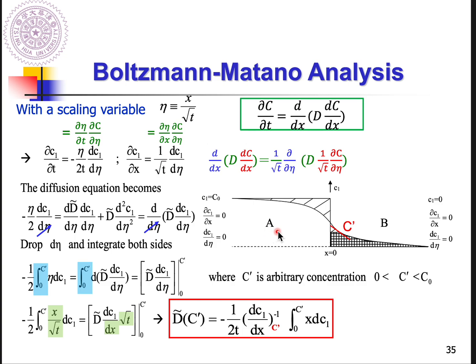Then after time t, you just section this diffusion couple and use element analysis equipment, for example EPMA or EDX or SIMS, to get the concentration profile of A. As long as you got this profile, then the diffusion time period is what you deal with, right?